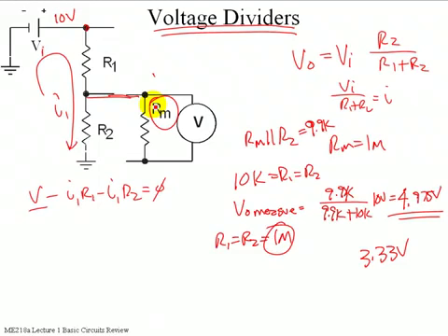In the back and then over here. What keeps you from using higher and higher resistances for your...? Well, this resistance here is the internal resistance of the meter. So the amount of current that is drawn by the measurement circuitry inside the device is equivalent to a mega ohm resistor.